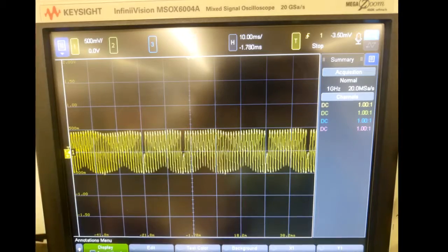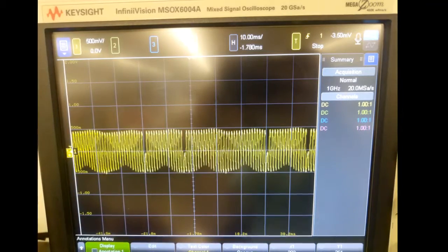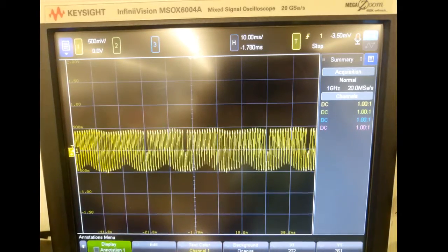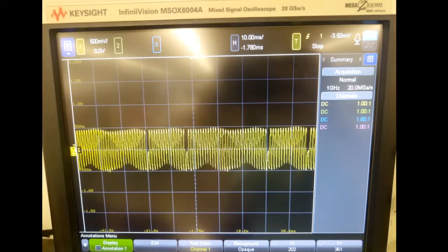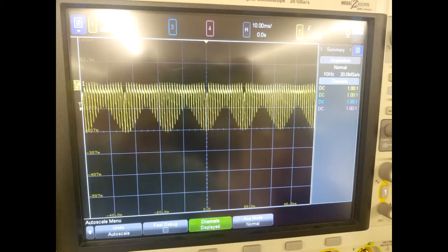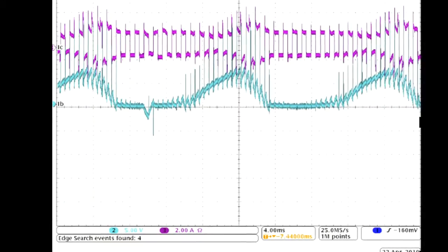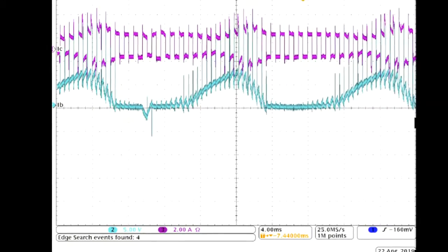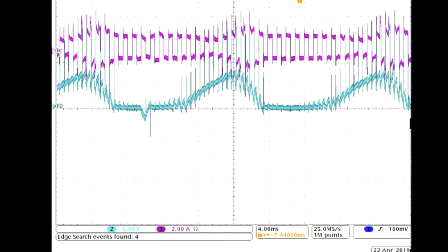In fact, the clear sine wave that you can see is 60 Hz, while the noise is 2 kHz, the second harmonic of the primary side. This led us to believe that the filter that we were using was not effective. We tried using many different combinations of capacitance and resistance. We also tried changing the code and changed the input frequency. Each change changed our output signal, but not in traceable ways. Eventually, after enough trial and error, progress was made.